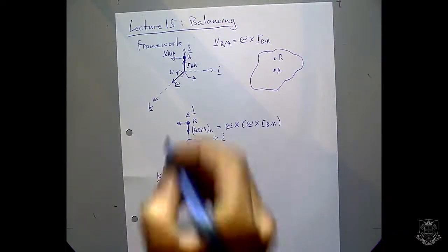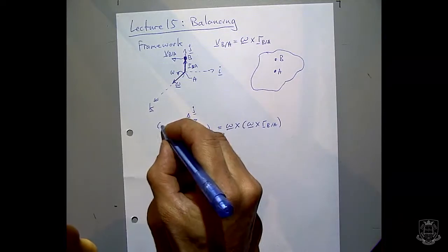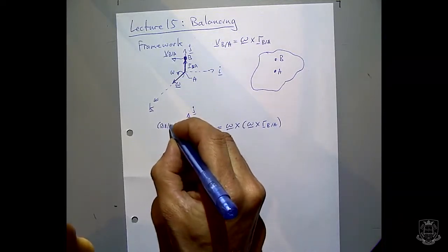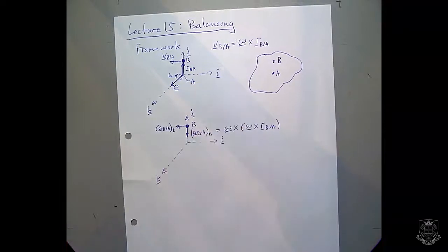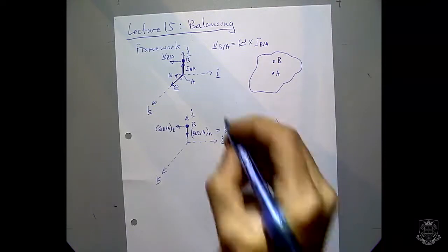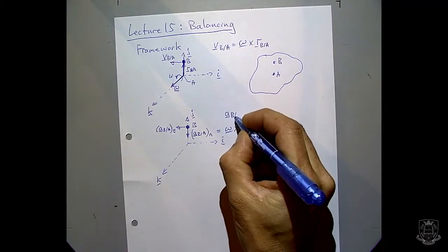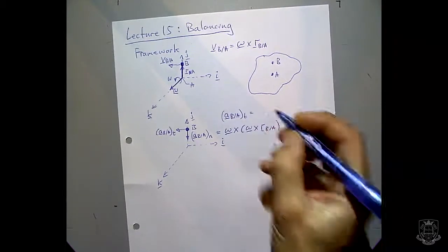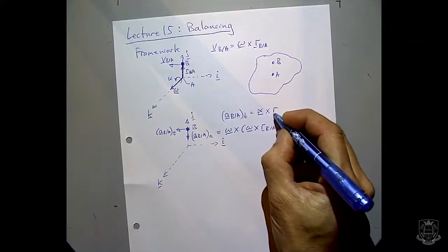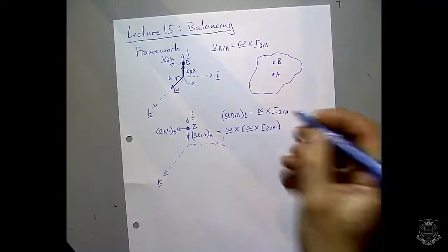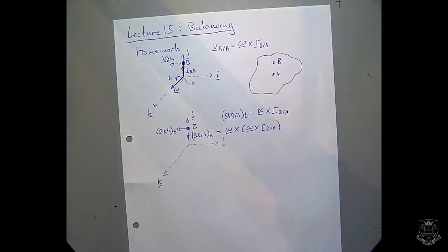And so by that logic, this component of the acceleration, A of B with respect to A, is the subscript T, or tangential part of the acceleration. Okay, so we sometimes talk about components as normal and tangential. And the acceleration that's tangential is equal to alpha crossed with R, where alpha is the angular acceleration of the rotating component.